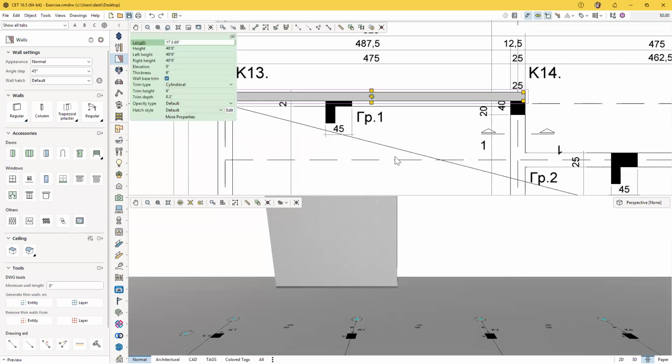So as you are creating walls using a CAD plan, you will get those purple lines that will pop up. And as long as your wall that you want to create is either where it looks like it is as you're placing it, or is in the purple outline, that purple ghost outline, either way, that will work for you because after you select your length, you left click, and then you can choose which side of the line you actually want to place it on.